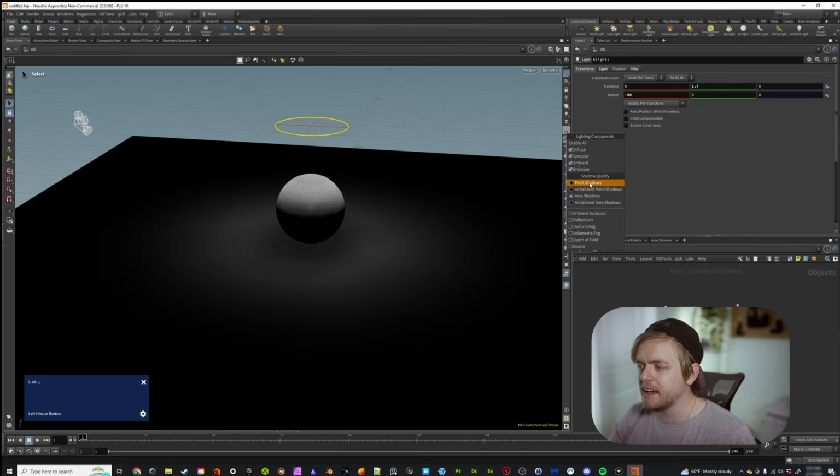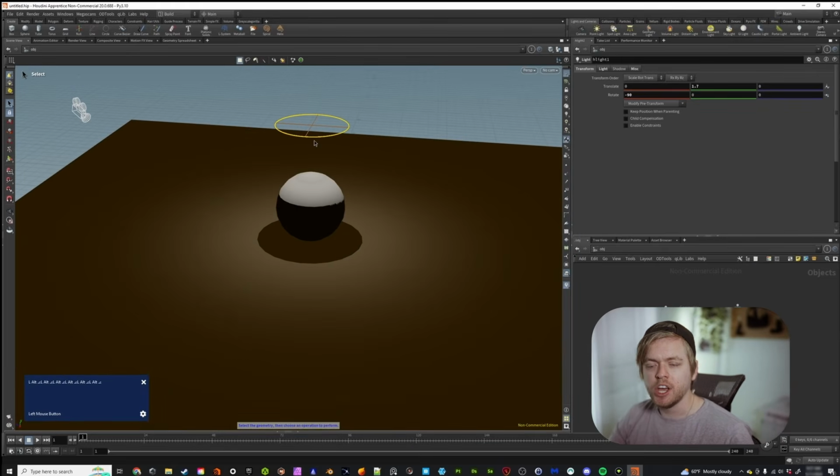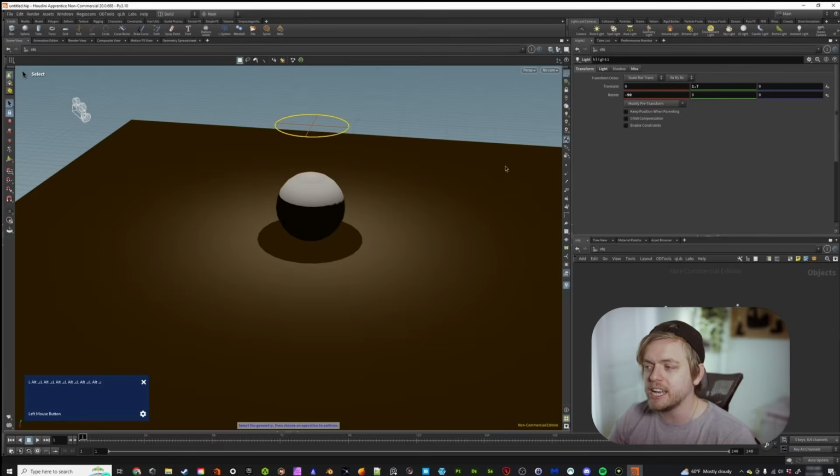Now, what you might have is point shadows right out the gate. That means no matter what the light source is, you are going to have these hard shadows. But the reality is, a quick lesson on light is the larger the source of light being cast on your object, the softer your shadows are, because the light is hitting it from more areas. Whereas one part of the light is casting a ray that is creating a hard shadow, the other part of the light is on the other side of the object and is filling in part of that hard shadow. So instead you get a falloff.